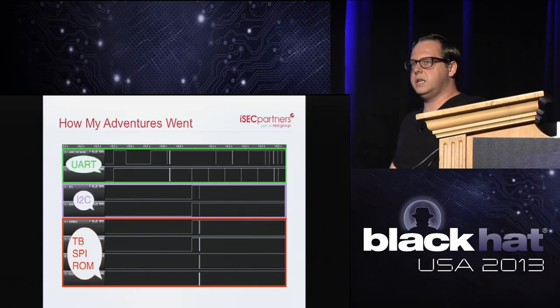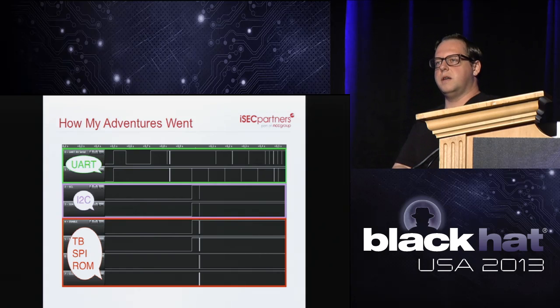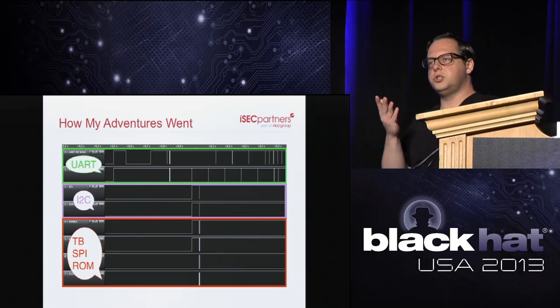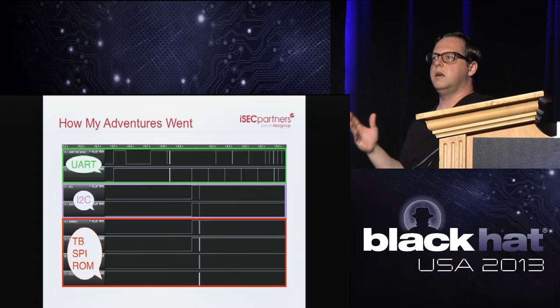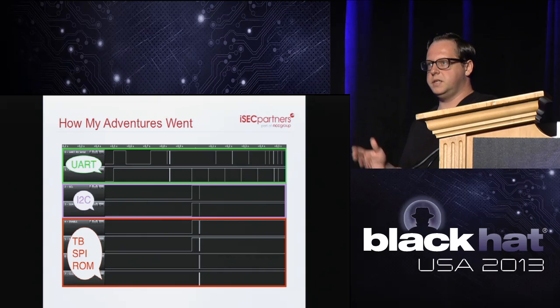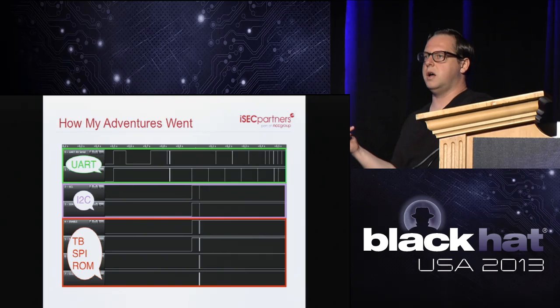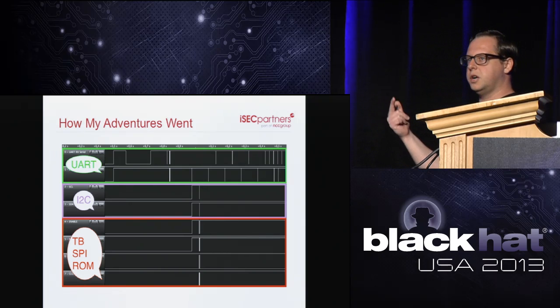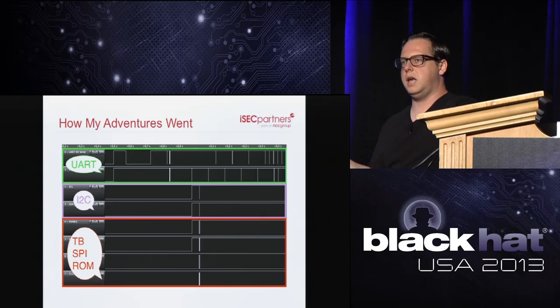It might be hard to see from this image, but basically the UART comes on first, and the UART transfers data even before Thunderbolt ever boots up. Thunderbolt isn't even hot yet. Once the ARM does its thing and gets programmed by the Apple, then Thunderbolt comes on. The I2C buses start communicating between the ARM Cortex and the Thunderbolt controller, and device information is now sent up to the computer through the Thunderbolt.